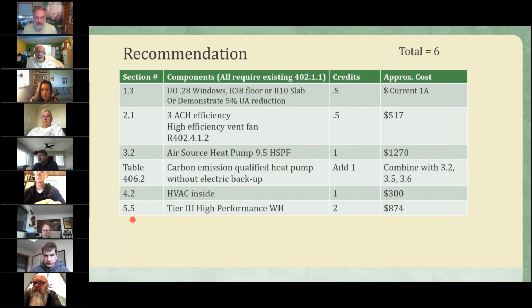Next. So the different tiers on the water heaters, it's basically a performance rating. So tier 1, tier 2, tier 3, there's actually a tier 4 category too. If you're taking tier 3 or tier 4, you get the higher points on the credits. They're generally better performing, better water heaters. I haven't seen anybody really leaning towards taking a tier 1 or a tier 2 water heater. They're either going with the on-demand gas water heater or with the tier 3 electric water heater.